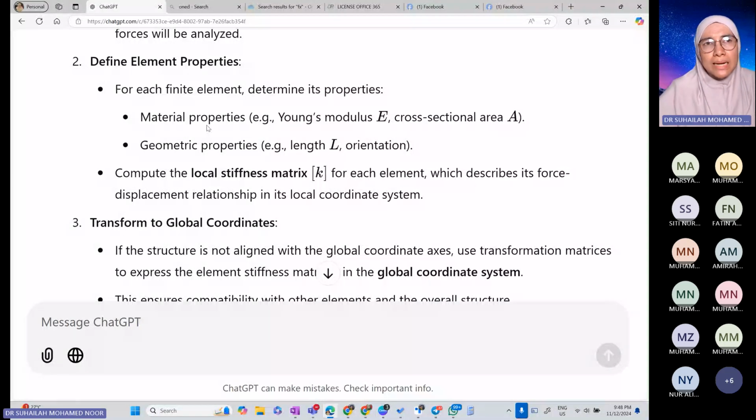So biasa berlaku bila kita check using dia simple formula only, dia based on the height of the building. Okay, adalah formula dia. Kita check kan displacement yang kita dapat from kita punya analisis guna software tu exceed the limit, lebih besar daripada allowable limit.